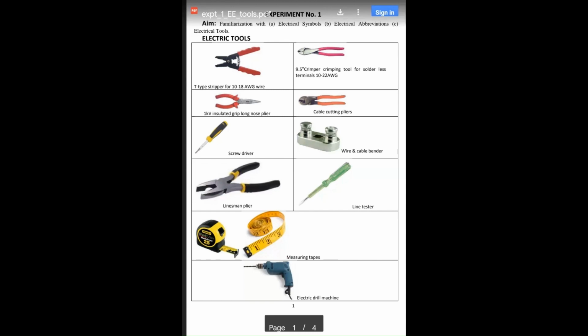So how can we differentiate between the 5 ampere and 15 ampere? The 5 ampere is a bit smaller, and it is 5 ampere slash 6 ampere, and similarly 15 ampere slash 16 ampere. It is the current which these terminals draw when the loads are connected to them. The 15 ampere and 16 ampere are the power switches, or the power plug which is connected to them.